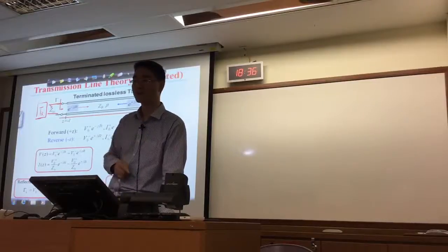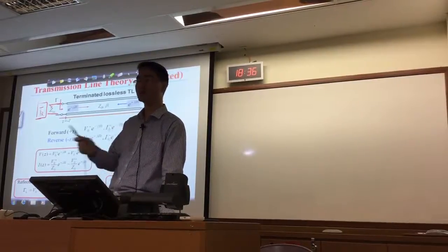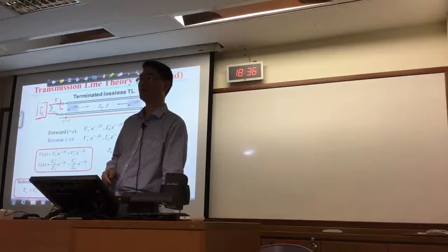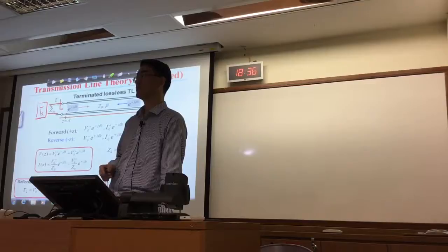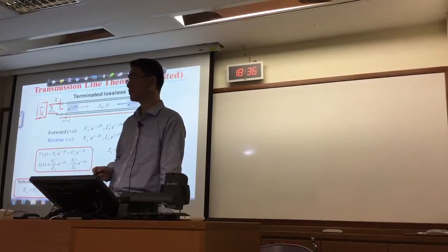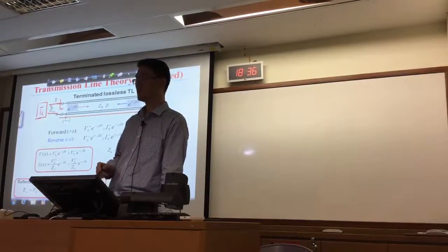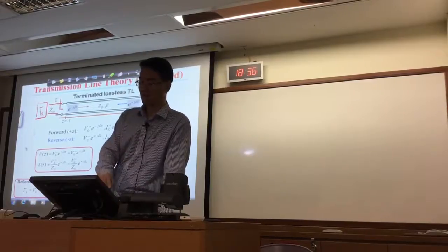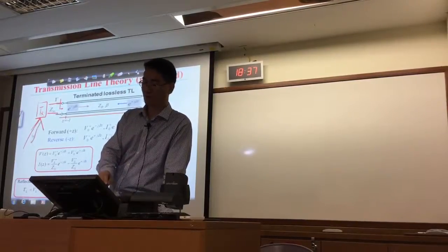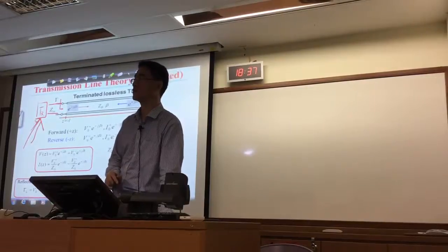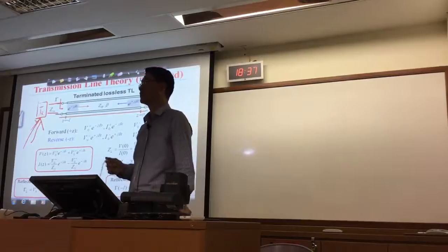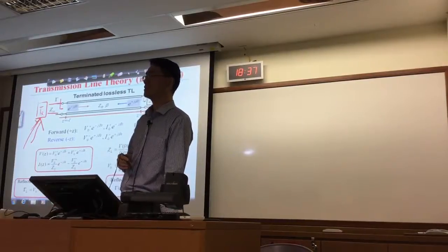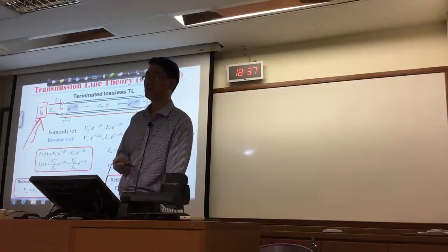For instance, for defense applications, I also mentioned a big phased array antenna, where a small percentage of reflected power will cause a lot of problems. Also, there is currently still a lot of challenge in transmitter design. Typically the power amplifier, the last stage of the transmitter, has very low efficiency. Typically it could be less than, for instance in radar applications,